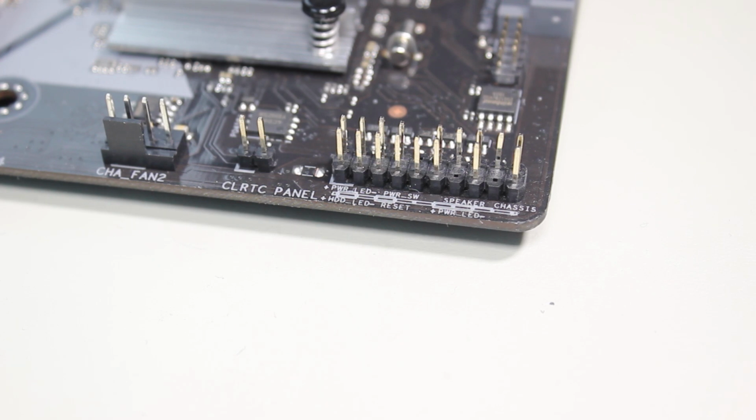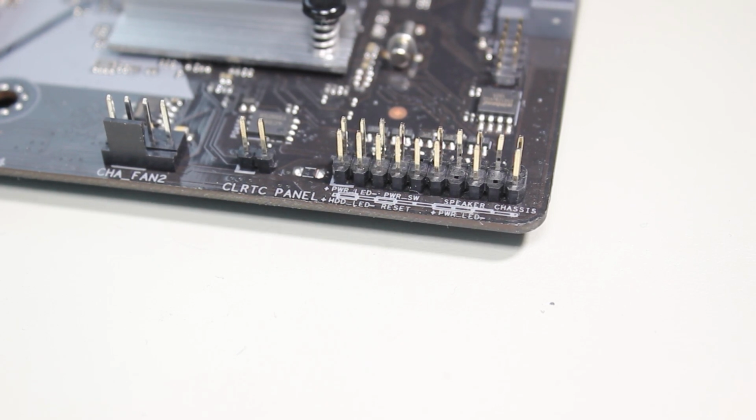The last connectors that need to be connected are what we refer to as the front panel connectors. These control the LED lights and switches on the computer case. For example, the light for hard disk activity and the power switch. On this motherboard, you can see they are found in the corner. Generally speaking, the front panel connectors on most motherboards are in the same place. However, on some motherboards, the pins for the front panel connectors may be separated, although this is rare.